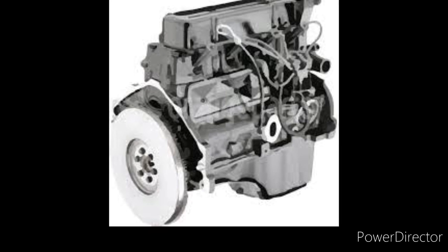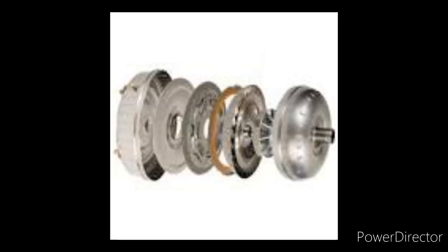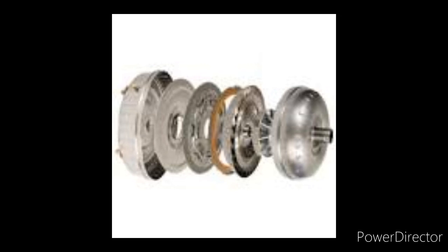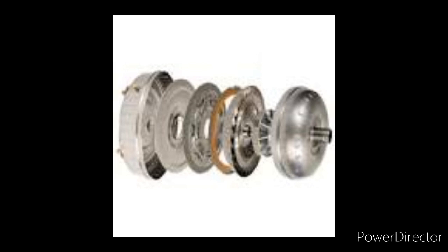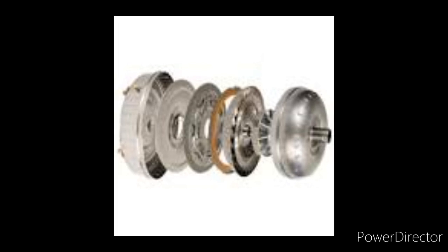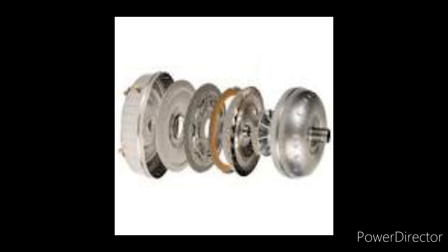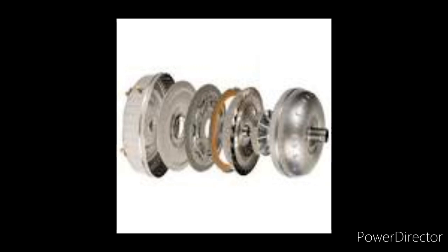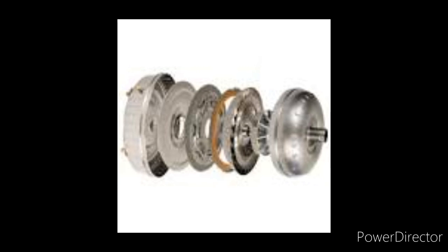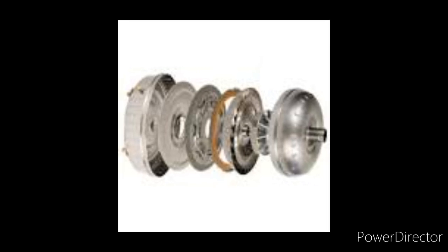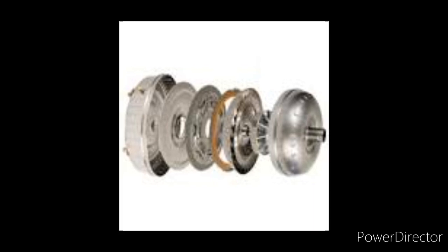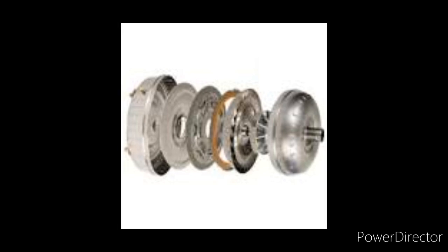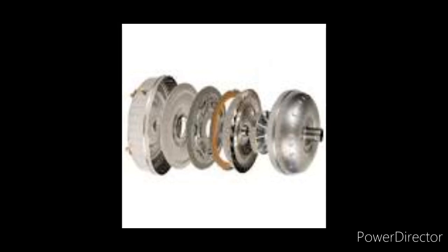Torque converter. In engine-powered trucks, this is a device that transmits mechanical energy from the engine to the transmission. The engine-driven impeller and stator drive hydraulic fluid into the turbine. The turbine begins to rotate at a ratio that multiplies engine power to drive the transmission parts. The converter is basically a clutch that uses fluid to transfer mechanical energy to the transmission gradually and without shock. The assembly allows the engine to run without the truck moving. In battery-powered trucks, the motor is directly connected to the differential or wheel hub.